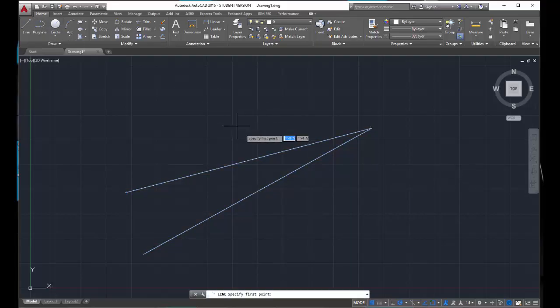Select a line. This time let's snap to the midpoint. Now here you see a triangle, whereas you see a square over here. The different shapes equal different places to snap to. So for midpoints, you're going to see a green triangle. For endpoints, you're going to see a green square. So let's snap to the midpoint of this line, and let's just go straight up. Click and escape to end it, and that is how you can connect lines together without having to continually draw things.